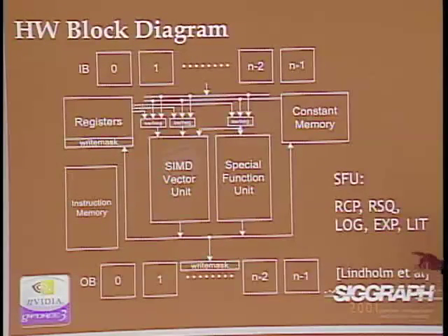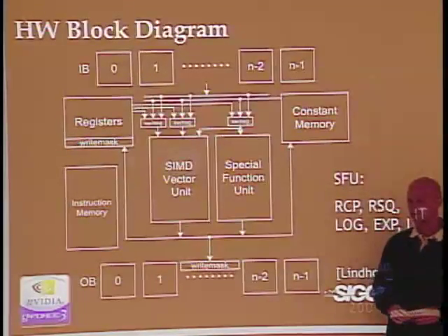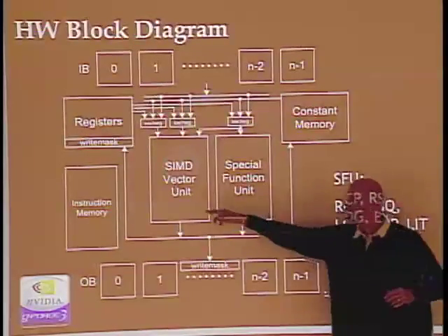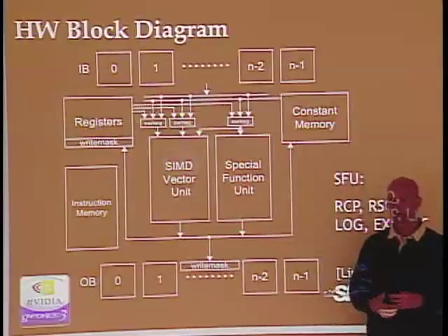Logarithm and exponent, and I'll talk about this one in a second. All right, but these are things where they're in the special function unit, and it only runs on 32 bits at once. Okay, so that was sort of their hardware trade-off. They said the common things we're probably going to put over here, and we're going to do them all 4 wide. The uncommon things we're not going to spend as much money. We'll just do them 1 wide.